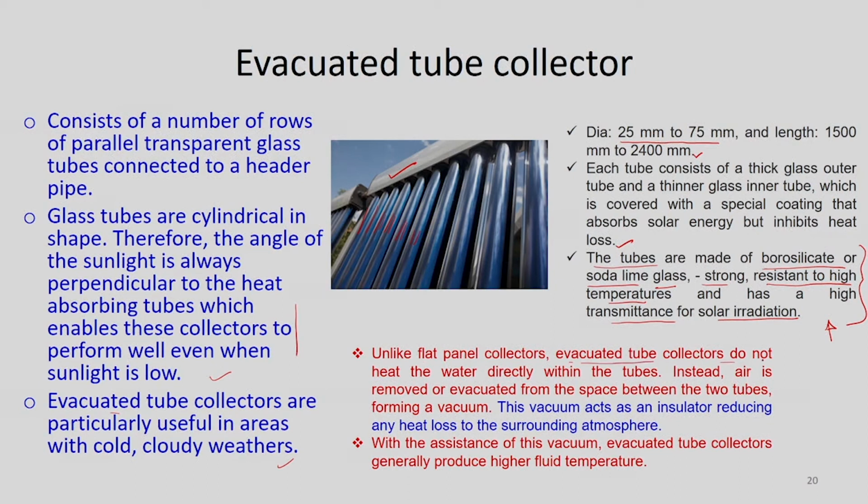These evacuated tube collectors do not heat the water directly within the tubes. Instead, air is removed or evacuated from the space between the two tubes, forming a vacuum. This vacuum acts as an insulator, reducing any heat loss to the surrounding atmosphere. So, these are the tubes.